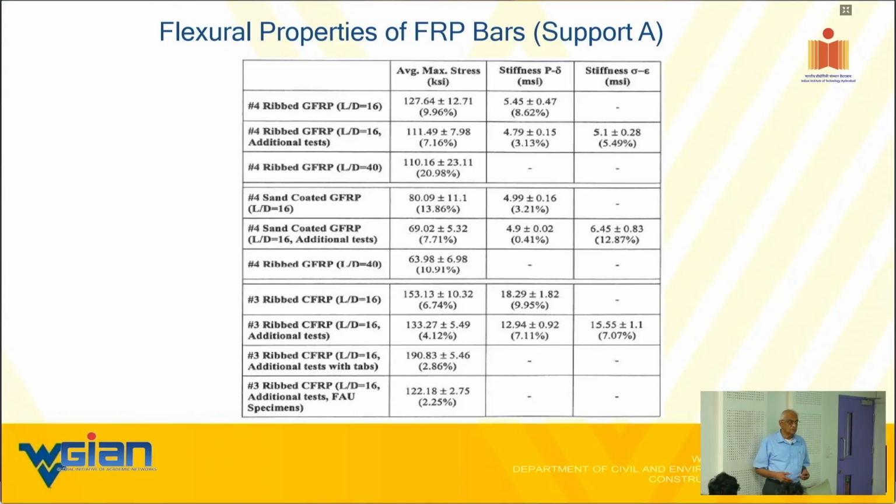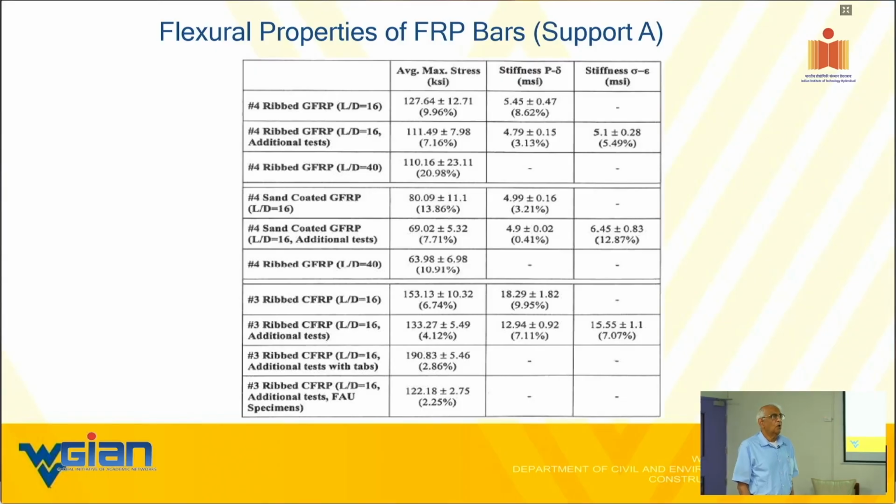Actually, sir, in lab testing we do compression testing. We did in our lab, the professor has also done it. What size? We did for different L by D, so I went for 10 by 10 by 10. No, what size column, not the rebar? In columns, I struggled with the same problem, sir. I did 300 mm by 300 mm, that is 12 inch by 12 inch. A few samples I could not do because they went more than 3,000 kilonewtons, and my machine's capacity is only 3,000. After I got a 12,000 kilonewton machine, I started doing it. Even that, I say, is low.